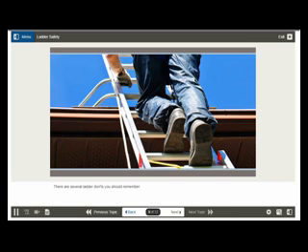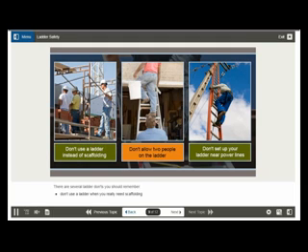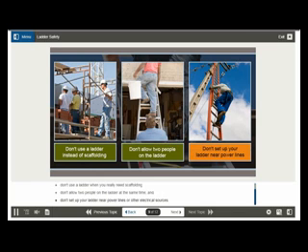There are several ladder don'ts you should remember. Don't use a ladder when you really need scaffolding. Don't allow 2 people on the ladder at the same time, and don't set up your ladder near power lines or other electrical sources.